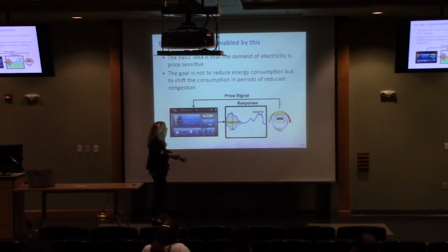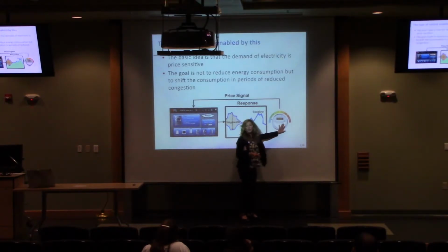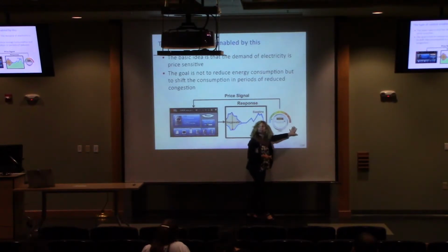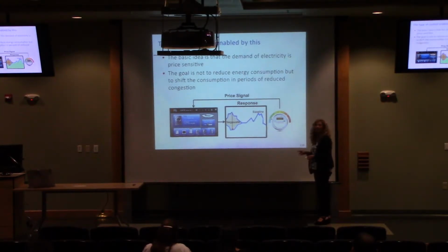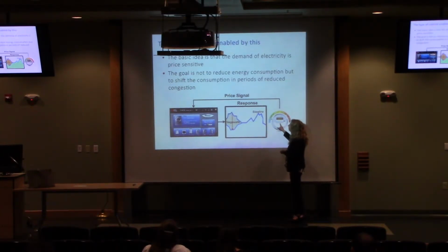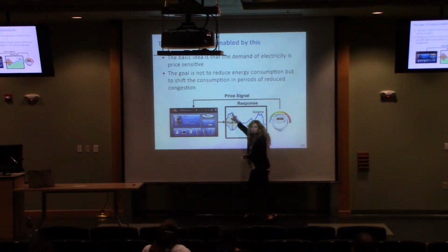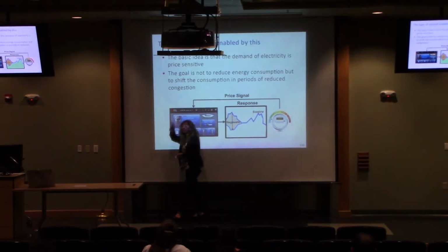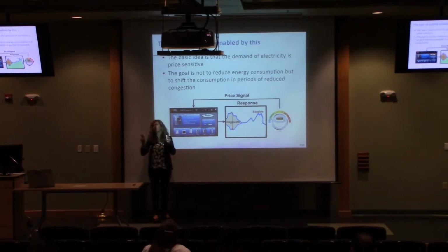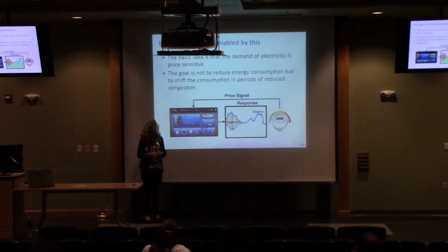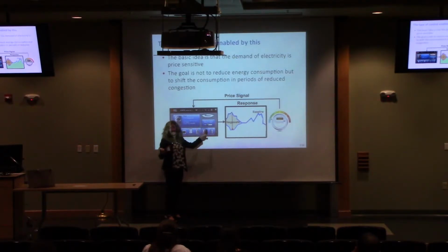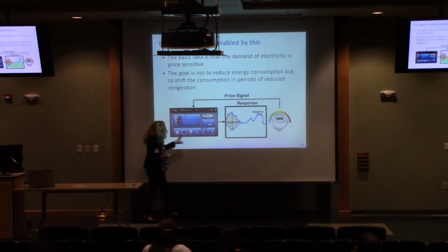Here is your AMI, right? And they are deployed right now. They are metering information. They are trying to reality check what you are consuming, but they're not really telling you to do anything. But the dream of demand response from the utility perspective is that they're going to send you a price signal, which will be computed in quotes and quotes real time. The real time will depend on a bunch of considerations, including the latency with which they can actually compute it and send it to you.